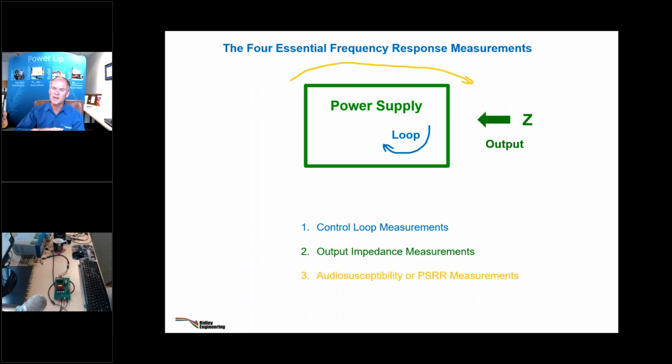And then the last 5 years or so, people started measuring it again. Why? Because they stopped doing current mode, or they've done LLC converters where they're just worrying about efficiency and they've forgotten about the importance of the loop, and they can see noise on the output again. Sometimes it's terrible noise on the output. So now people have started speccing and measuring line to output or power supply rejection ratio. So that's important.